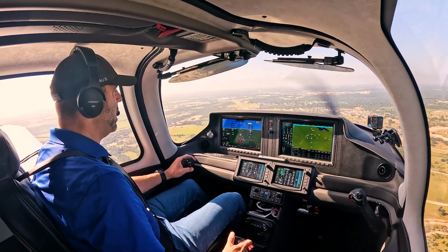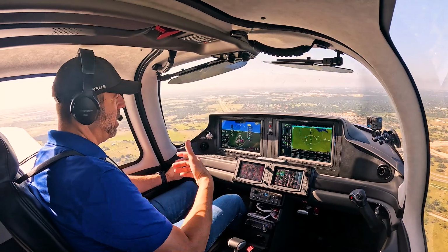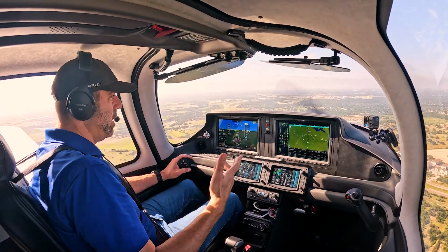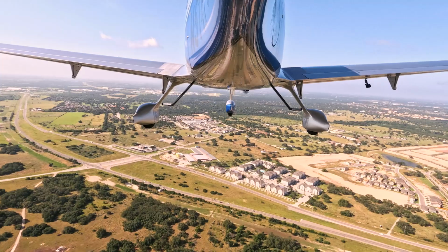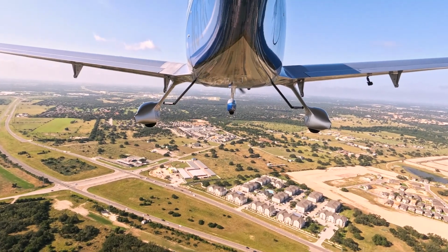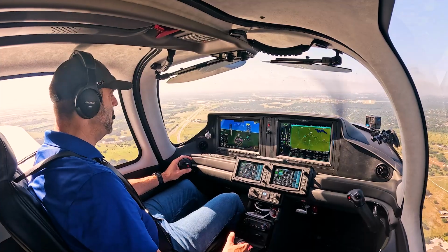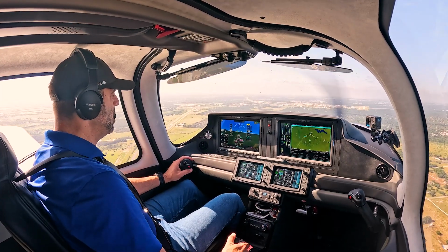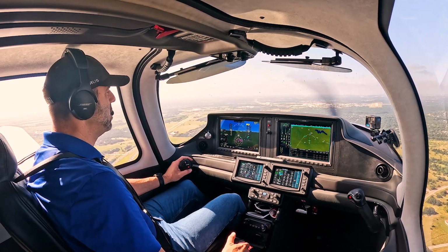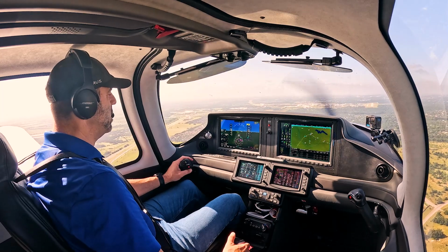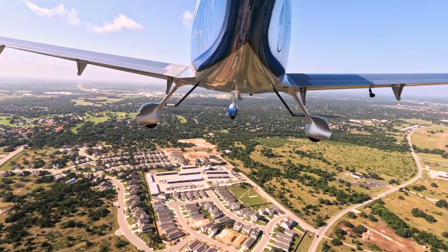So let's slow back down. We gained a little bit of speed, right? I'm not going to let that tailwind catch up with me. So let's refocus, pitch up a little bit, bleed off some of that airspeed. There's 110. Power back to 15%. Roughly, there's 100 knots. All right, speed checks below 150, which we are.